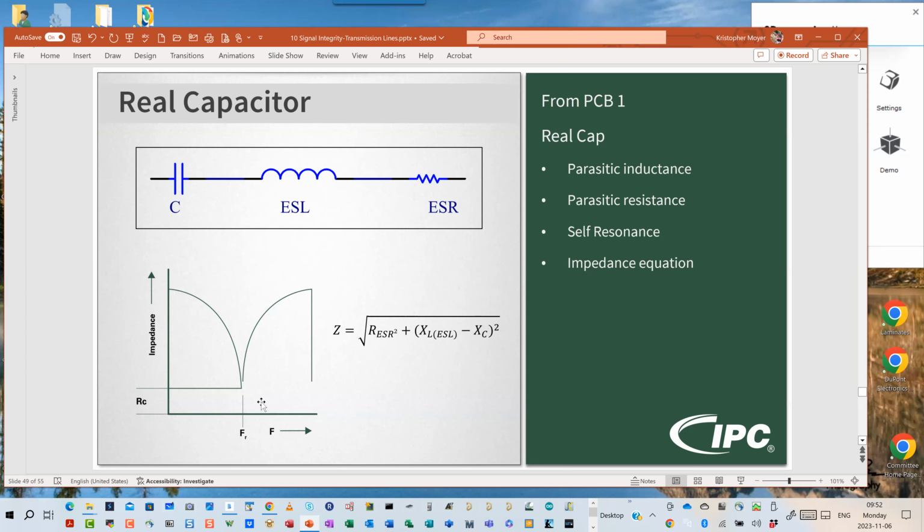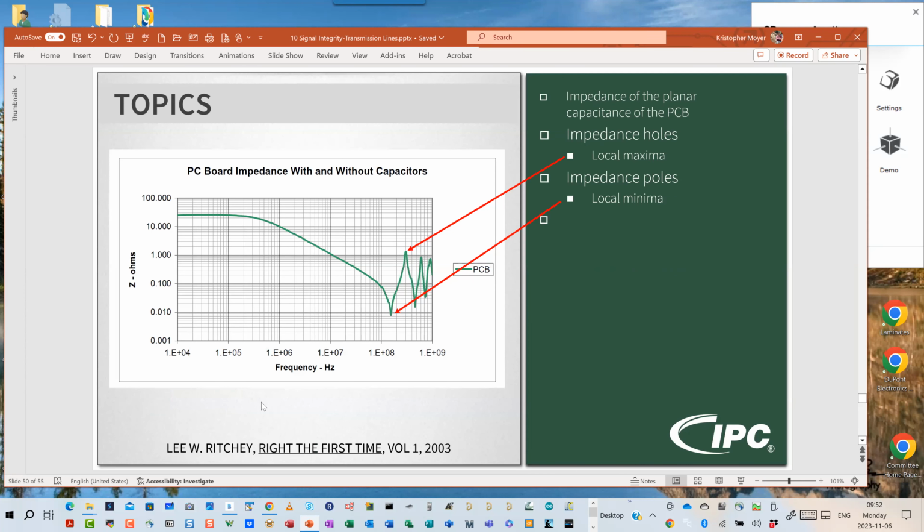So because of this, what we are going to have now is a behavior of our capacitors for our board. Now, I said that the capacitor of our board has near zero inductance. It doesn't have zero. It will have a little bit of erroneous behavior, and we'll need to do a frequency versus impedance sweep right here to characterize the overall impedance response across all frequencies.